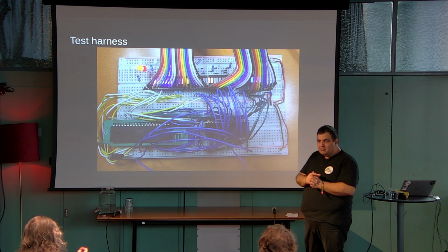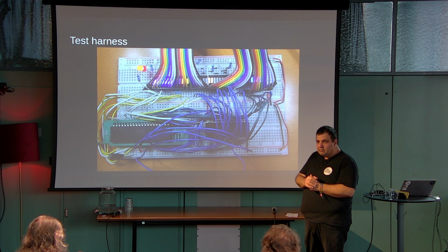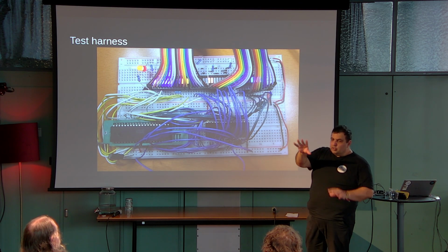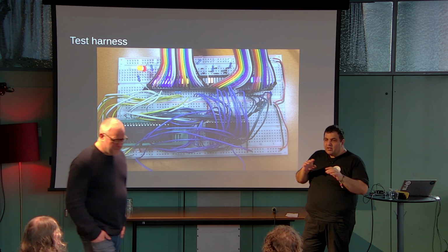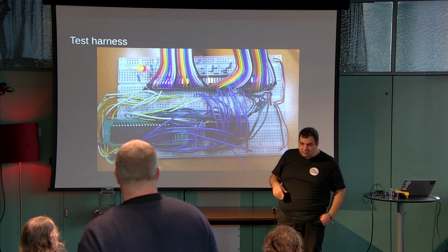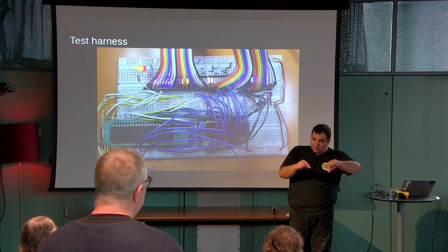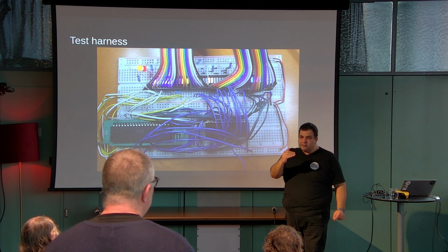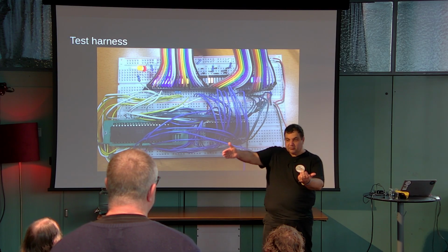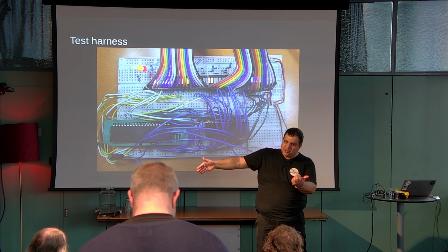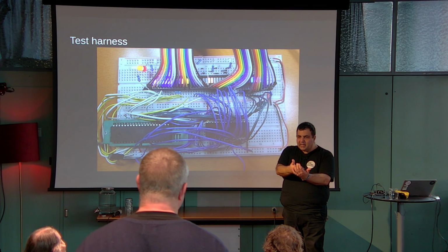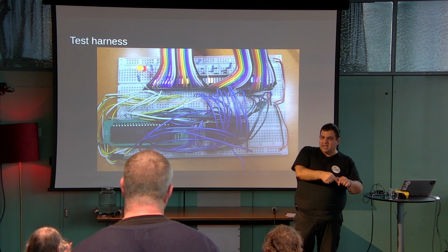Yes, and not just on the bus, but behind, for example, if you have an instruction that adds or rotates, how would you sense that? Just by looking at the signals, you can't sense that. It doesn't expose state at that stage. But since I wrote the test program, what I can do is that every time after I add two numbers, I dump the relevant register as well as the condition codes. And this way I can make sure that the internal state updated correctly.